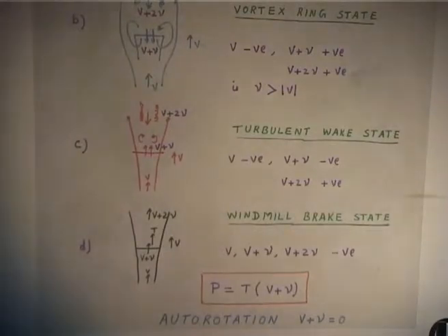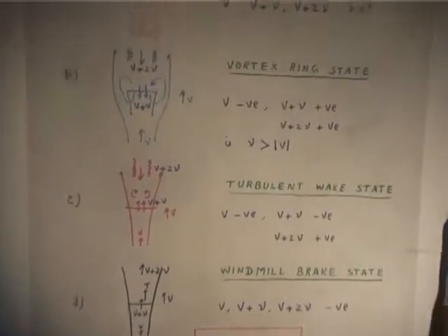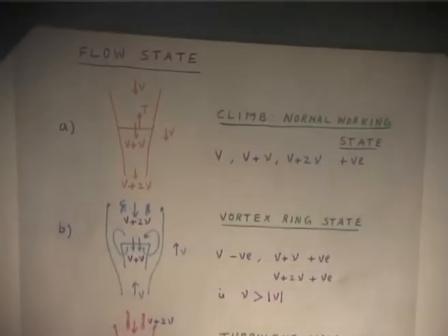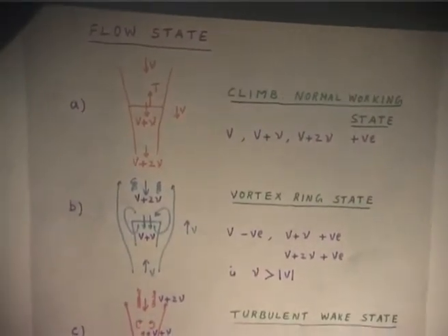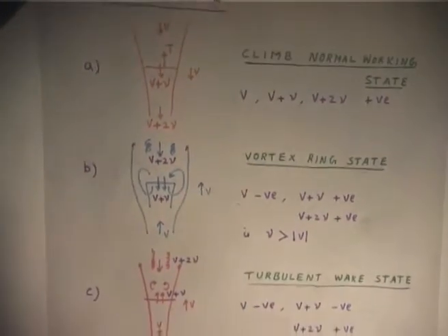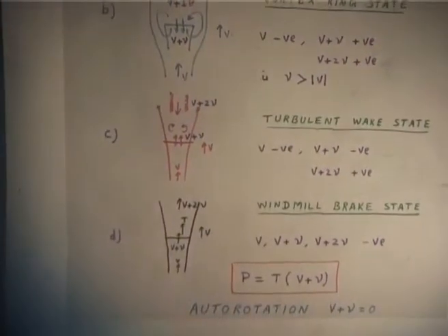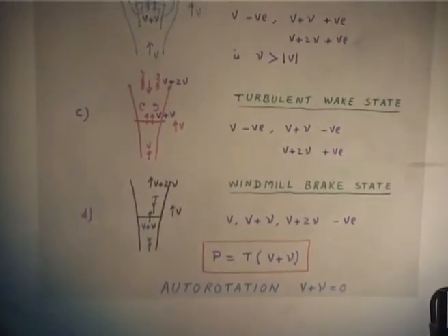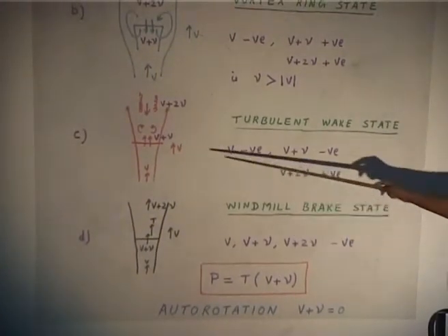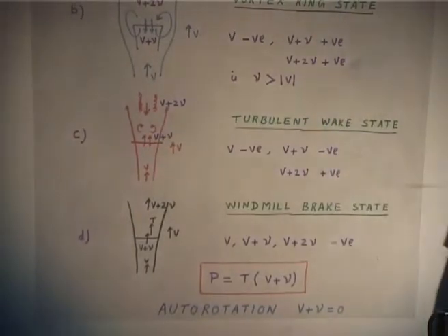So, we first assume, but please note now what we derive today, maybe next class. In this state, momentum theory is valid, because everywhere the flow is the same direction. This state, momentum theory is valid, you can get the inflow, but in these places there is no theory, please understand, you do not have any theory to get what is my inflow at that time. In vortex ring state or in turbulent wake state, what will be my inflow?